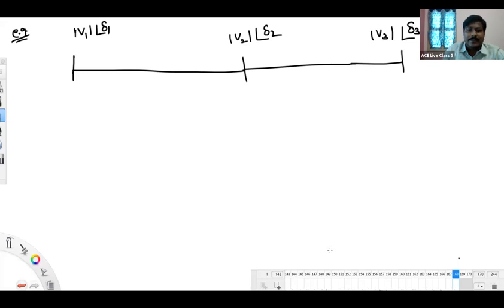These are all approximate equations only, by considering X. All of you, please tell me which bus you want me to take. Bus 2? Okay, fine. Bus 2 I'll take. Listen. I will have two paths at bus 2. This is one path, Q23, I will say. This is the other path, I'll call this Q21. Could you please tell me what is the Q23 equation?